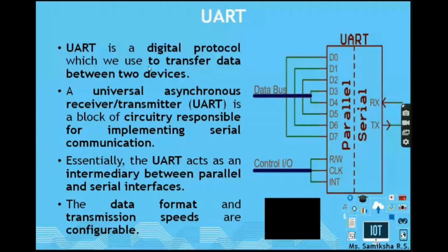So what does UART stand for? UART stands for Universal Asynchronous Receiver Transmitter. This circuitry is responsible for implementing serial communication. If you want serial communication, but your device is a parallel device, then you have to implement a UART over there. So UART circuitry will help you achieve serial communication with a parallel device.